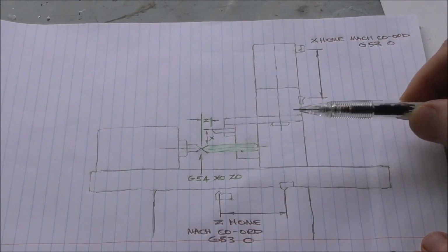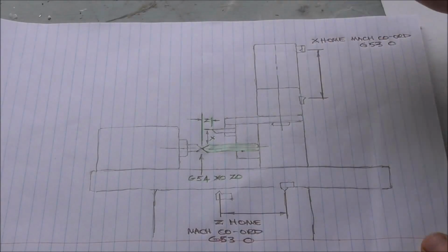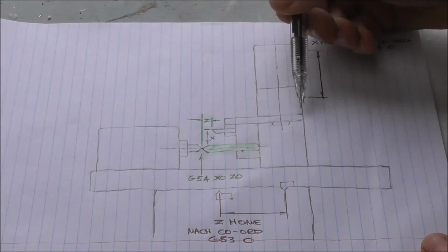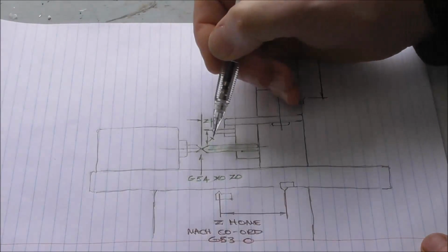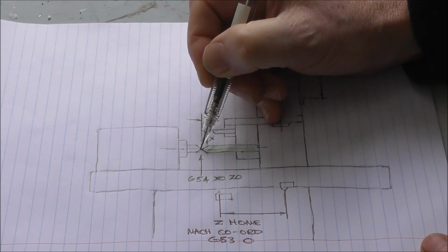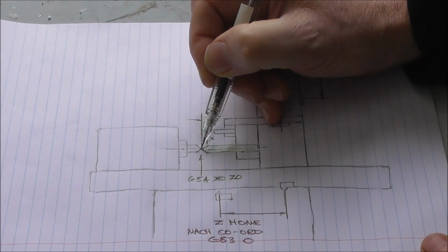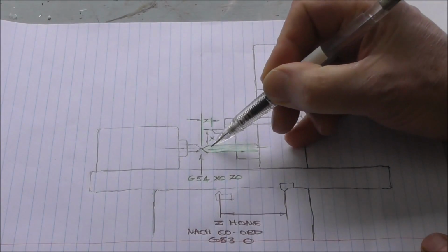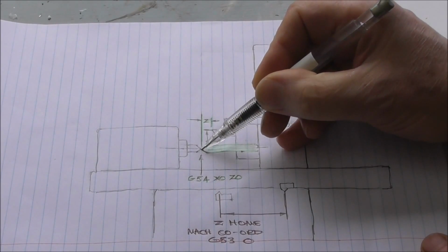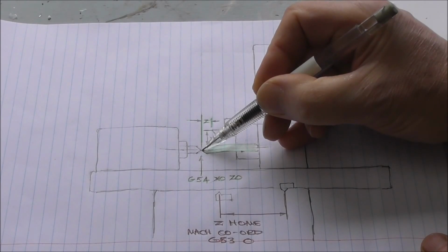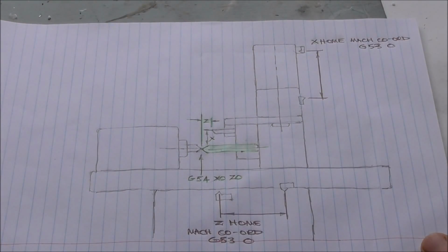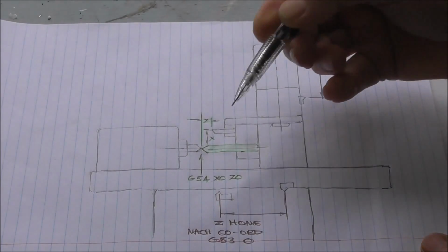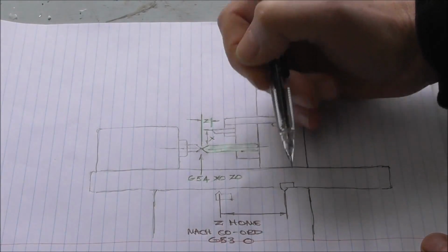Let me try and explain this with a schematic drawing. I'm just drawing up now our setup. So okay, here's our vertical column, here's our tooling platform, here's Rapidturn, there's our work. We've got a pointer referencing showing the X, Z center point there. We're using in green a master tool. Let's call it a green master tool with a pointer showing the control point touching the key point on the work. We're showing our homing switches here in the vertical, which in the lathe form is the X, and the longitudinal, which in the lathe form is the Z.